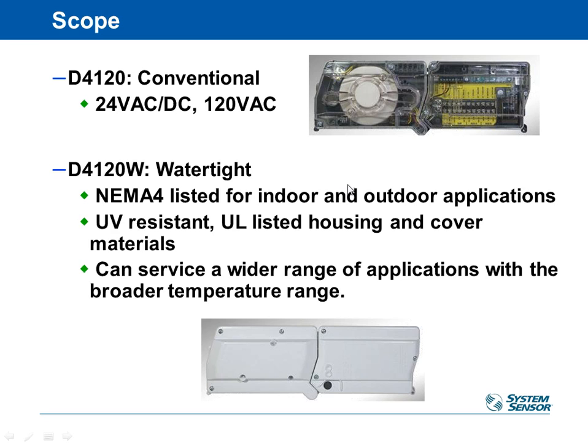Same thing is true on the outdoor version. The outdoor version is basically the exact same product with the same wiring label terminations and works the same way, looks and smells like the exact same thing. The difference is that it has a different cover that is UV resistant and it's rated for outdoor usage. So the cover, the plastic itself, is white and UV resistant, and the way that the box seals is NEMA 4 rated, which means it's watertight. So it can be installed outdoors.